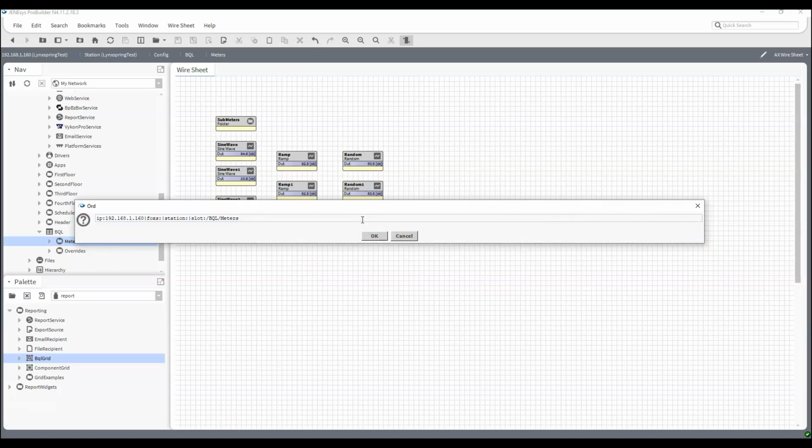So now let's go ahead and go BQL select, and now we're going to say display name, and we're going to take the sum of the out.value from the control numeric point having sum of out.value greater than 50.